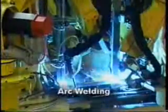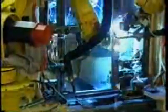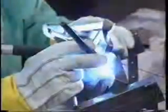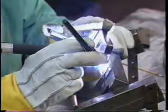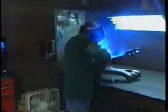Arc welding processes use an electric arc as the heat source to melt and join the base metals. The arc is struck between the workpieces and the tip of an electrode. Arc welding electrodes are usually consumable, but can be non-consumable. The consumable electrode is usually wire or rod, and the current that sustains the arc also melts the electrode so that it supplies filler metal to the joint.